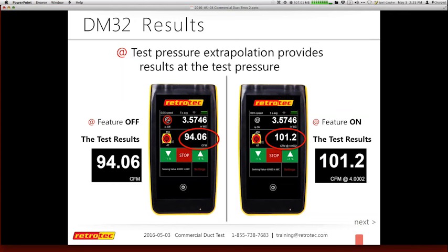The first option is that the fan itself has a speed control knob on the DucTester, so you can use it versus using the gauge or software if I really just want to dial in my test pressure. Some people are more comfortable with that, and then after you get more familiar with it, you can use the gauge itself, or you can also use the software that's on the next screen. So here, as I showed earlier, you can just use the set speed feature, where I just hit set speed and jog up the speed until I reach the test pressure or the max test pressure that I can achieve. And I can use the add features and all that.